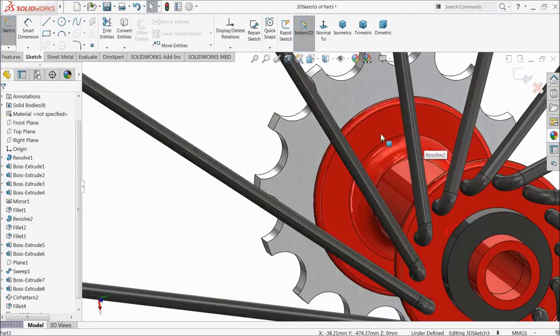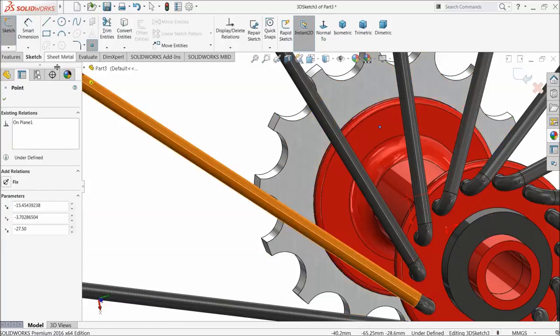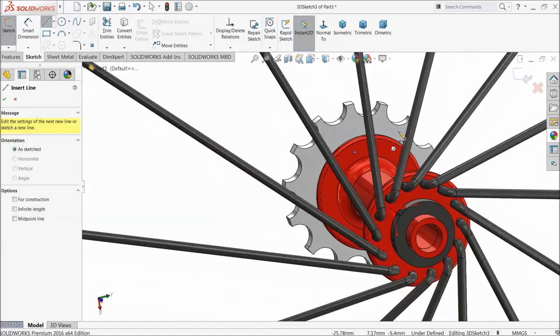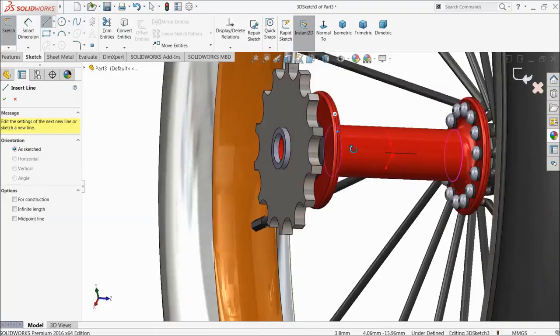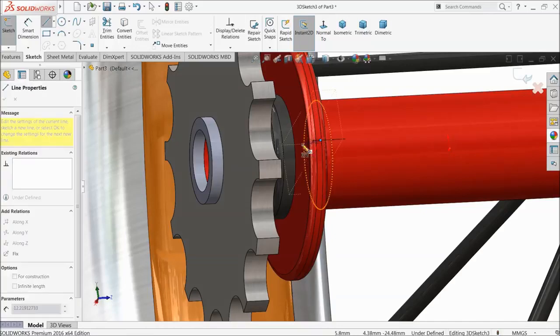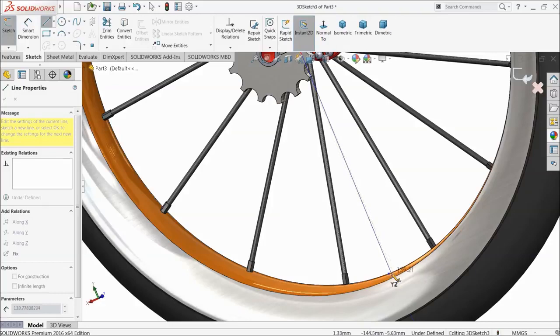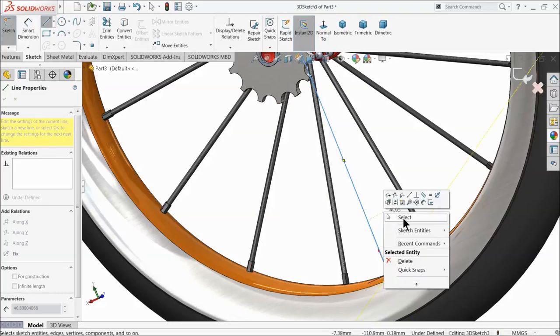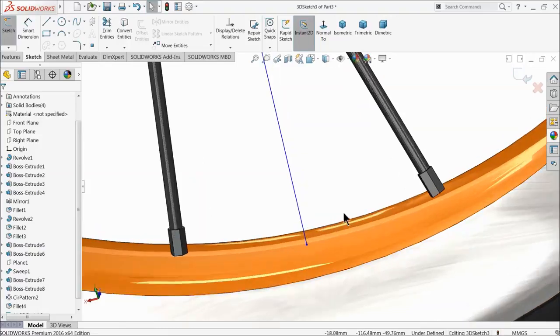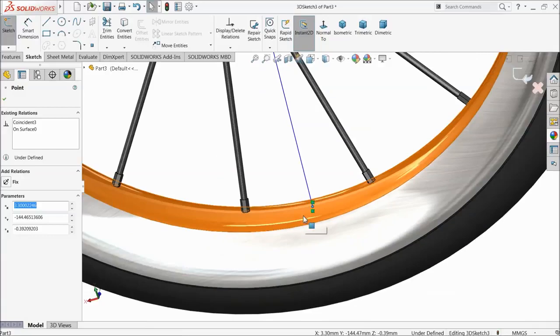Now let's choose this point, star. Okay. Now let's start. Select line, select this point, press tab key, this direction, and drag your geometry and connect with this point. Exit. Now just try to adjust your point if you feel something.